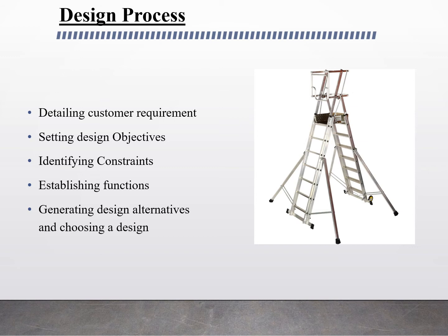After generating design alternatives, you need to model and analyze the design with questions such as, what is the maximum stress in a step supporting the design load? How does the bending deflection of a loaded step vary with the material of which the step is made? So after analyzing the design, you need to test and evaluate the design with questions such as, can someone on the ladder reach the specified height? Does the ladder meet client's safety specifications?